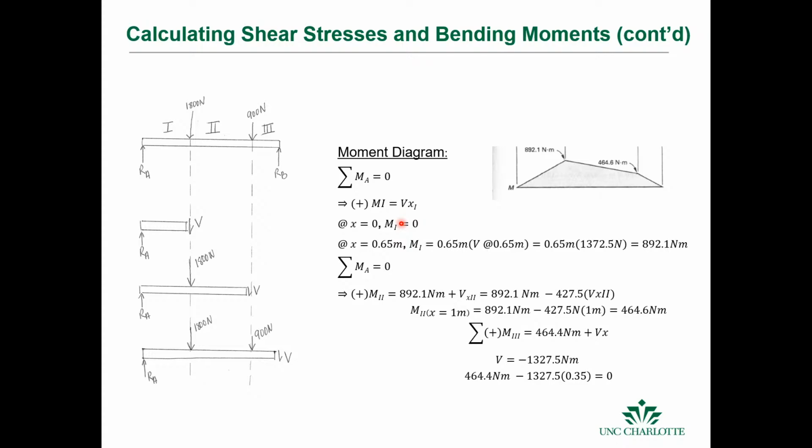We can then calculate the moments, because if we know the load on an object, and the moment is the force times the distance, it turns out that we can take the integral of the shear diagram and get the moment diagram. Another way of doing this is if we sum moments to 0 about a point, then we have the shear at that point, and the further along we go, the higher that moment goes. And that's what we see here.